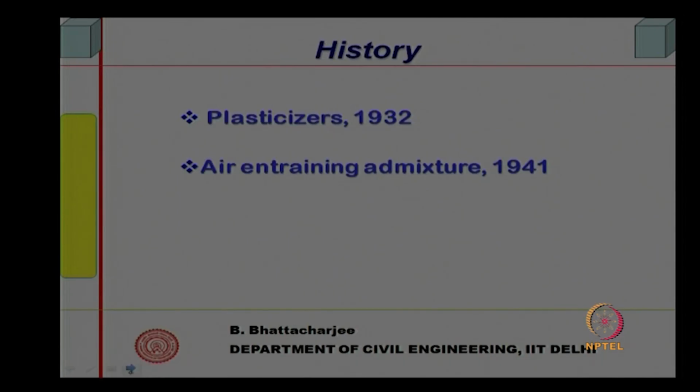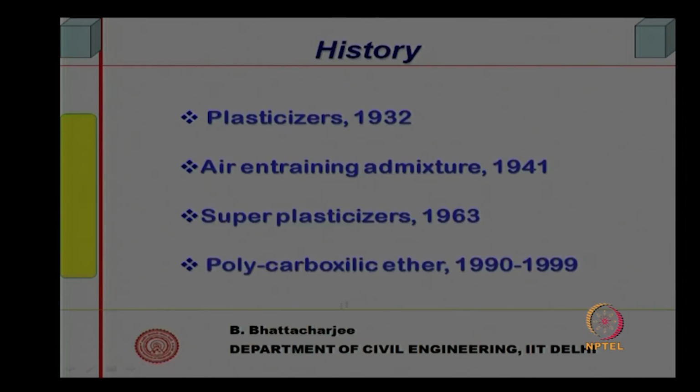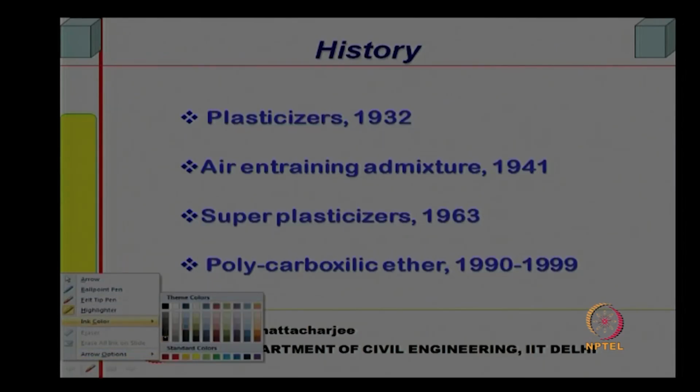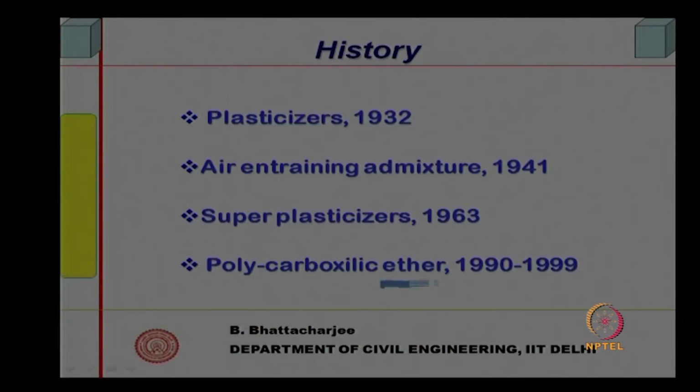Air entraining agent is an admixture used mostly in cold countries, which came in 1940s, and very high range water reducing agents came in 1980s and 90s. So, plasticizer 1932, air entraining agent 1941, super plasticizer 1963, and these very highly effective high range water reducing agents, polycarboxylate ether, came in 1990 to 1999.